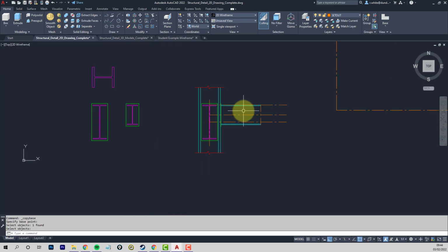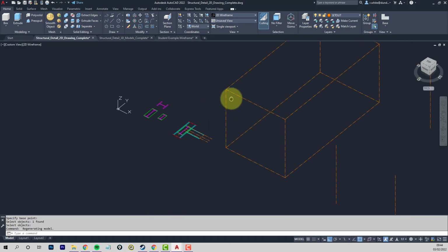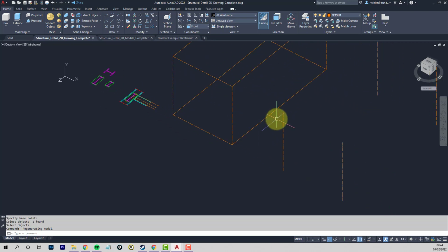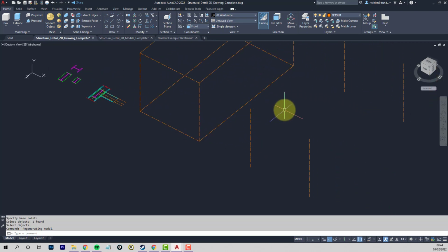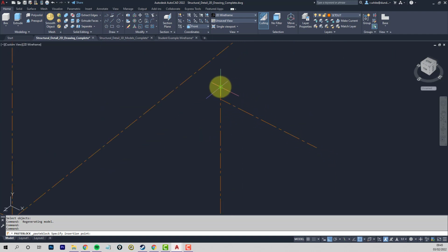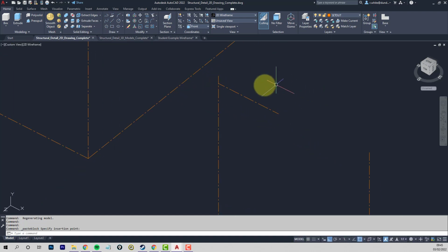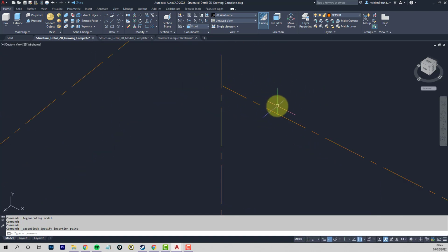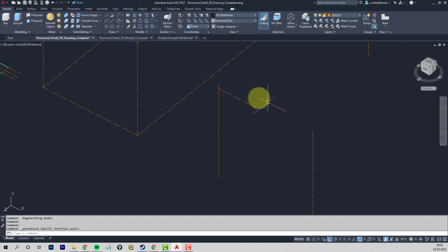Enter. Okay, now we go back into 3D. I go into that coordinate system, so it's the front. Okay, and then do Shift Control V, and I'll have the line at the end of my cursor. And if I pick the top of my column, it's set the center line of the beam at the right height. So I'll explode that now. X, enter, pick the line, enter, because when you do the Shift Control C you're creating a block. I can't stretch it if it's a block.